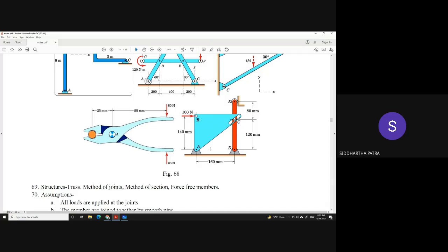So we'll now try to solve this problem right here. Can you draw the free body diagrams? If I want to figure out even the ground reactions, I need to draw the free body diagrams of individual components. So in this problem, because it's a collapsible frame with 2 additional degrees of freedom, we'll draw the free body diagrams of the individual components. So draw the free body diagram of the member ABC and DCE.